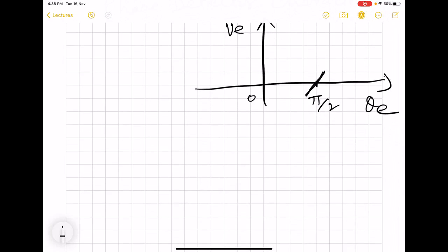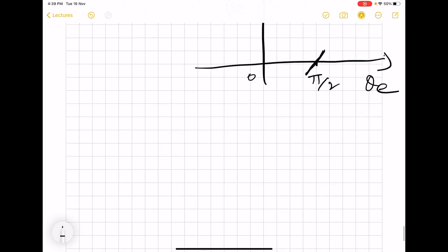So in general, this is the problem with the analog phase detector. So we are now going to talk about digital phase detector. That means the signals are now going to be a digital signal. That means square wave. So before that, we will try to see what we mean by the phase of a digital signal.